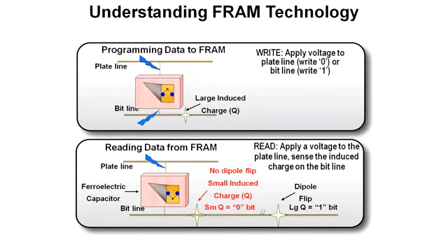A single FRAM cell can be considered a dipole capacitor that consists of a film of ferroelectric crystal between two electrode plates. Even though the term is ferroelectric, there's no iron material involved. Writing to FRAM requires polarizing the crystal in a specific direction using an electric field. This makes the FRAM very fast, easy to write to, and capable of meeting high endurance requirements.